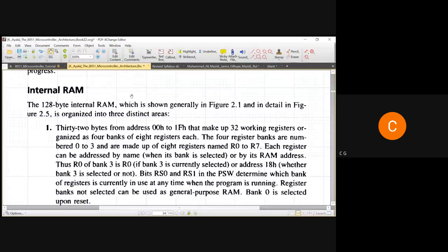In 8085, which is a complex instruction set, you will see there is only an addition command, but no multiplication command. So if you want to multiply two numbers, you have to add one number by the second number times. When you say 4 into 5, you give a cycle loop, add 4 five times.